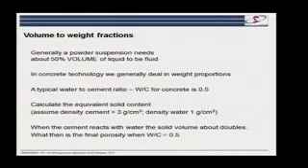And then in terms of basic concrete, we talk about water to cement ratios. So a typical water to cement ratio for concrete is 0.5. What does that mean? That means for every 1 gram of cement, we have half a gram of water.